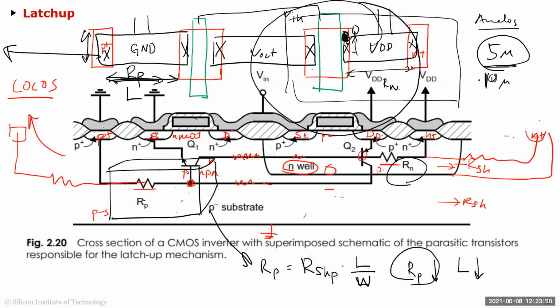People have got burned by getting latched up, because once you get a latch up, sometimes it is very, very difficult to debug. People use infrared cameras to see where the heat is coming from. A lot of times you still don't know, because these are all parasitic devices, and you would be scratching your hair, but somewhere you would have had a small gap in connection, and that would be latching it up. So that's why you have to be very, very disciplined in making these substrate connections spread all throughout.